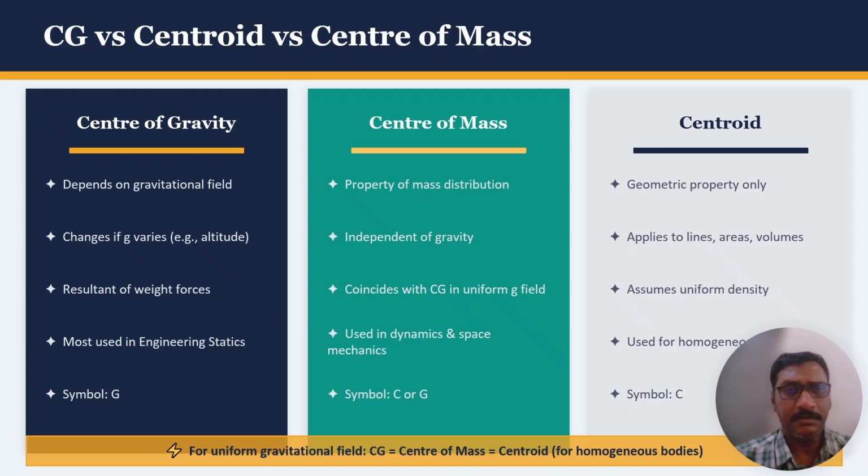Now the centroid. The centroid is a purely geometrical concept. It has nothing to do with gravity and nothing to do with mass. It is simply the geometrical center of a shape. Whether the shape is a line or area or volume, whatever it may be, the centroid is calculated based purely on the geometry. So it is the average position of all the points in that geometrical shape.